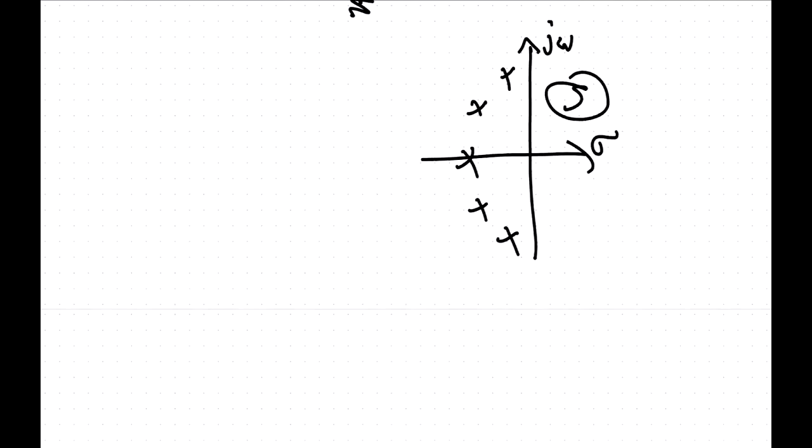Because according to our design, there is a shift after our scale down. Yes, but you see, I'll write it to you. This should not be ambiguous. If you want to linearly map, you want to have Vin, you scale that by 0.1, and you add 1 volt. That is what you have to implement.